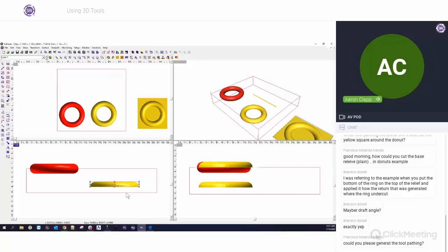Because what happens is there is some glitching when creating exact vertical surfaces. The toolpath tends to want to grab and create some weird things going on there. So if you can avoid it, what we would say is create the dome part and then just leave it off the edge of the material or off the bottom of the material, and that will naturally create a vertical bottom here of a certain distance. So when I go to cut this out, I'll 3D cut all of the dome part, and then I'll just run an end mill around the edge, and that'll give me a perfect vertical edge going all the way around. That's how I would probably deal with that.